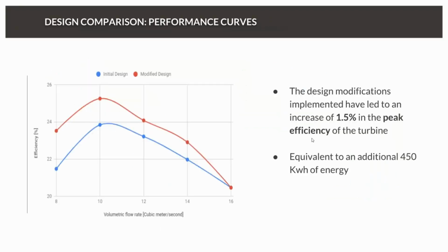Okay, so the interesting thing for me is that we took a design and we have made it better despite making one thing worse. So we've increased the efficiency, so we would get more energy from the water. And you can see on the right what that really means. The interesting thing is if we spent more time and really focused on either the design of the volute to direct the flow better through the stator, or we started really messing around with the stator angles and design, we could improve this much further.